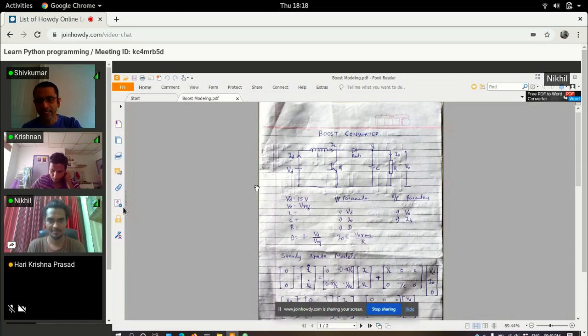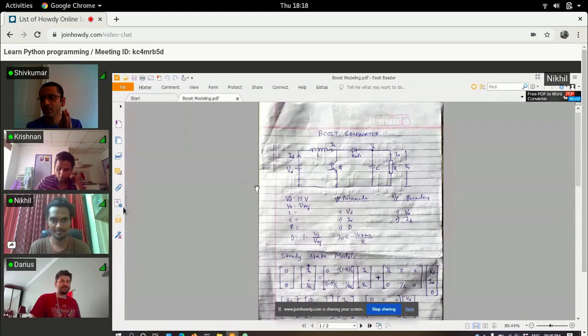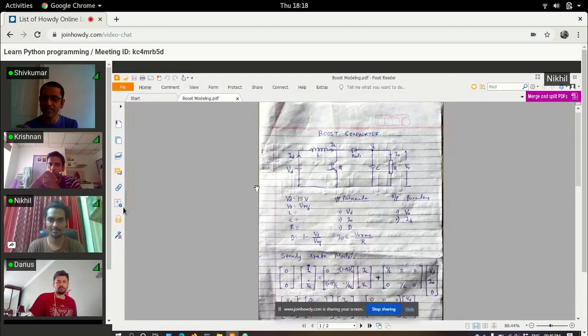And then there is a MOSFET or an IGBT, some kind of semiconductor device which can switch on and switch off. So it can be on a low resistance path, which is almost a short circuit, or a high resistance path, which is pretty much open circuit. This is different from analog circuits where there is an active region. In power electronics, you always work in the cutoff region, that is high impedance, or the saturation region, which is like zero or negligible impedance.